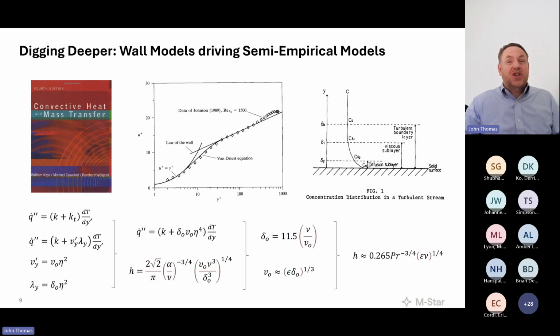We may know the energy dissipation across the system. Like, we could look at, say, a flow over a bank of tubes. We know the pressure drop and flow, which gives us power in. The first law requires that's related to power dissipation. So we can calculate the average power dissipation in the system and maybe use that, but that doesn't work very well. We really, really need the energy dissipation along the wall to make this correlation work, right? We need to know what the EDR is adjacent to the boundary layer in order to use these boundary layer theories to properly predict convective mass transfer, heat transfer.